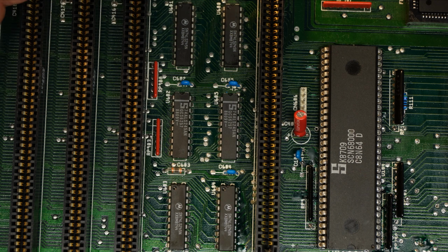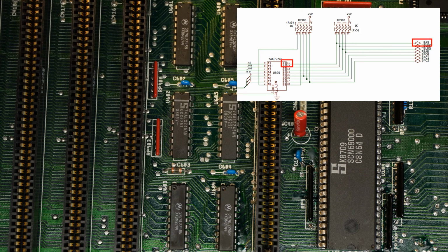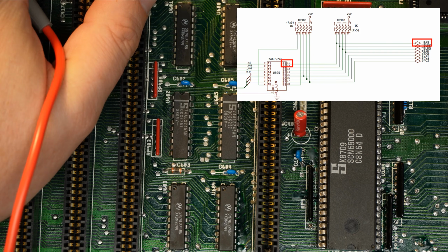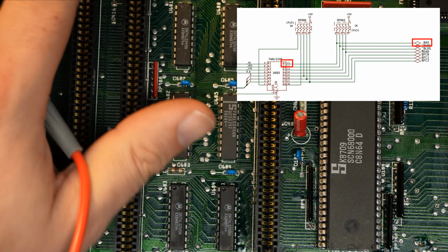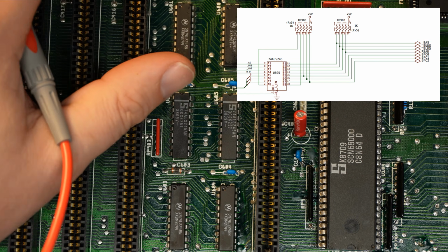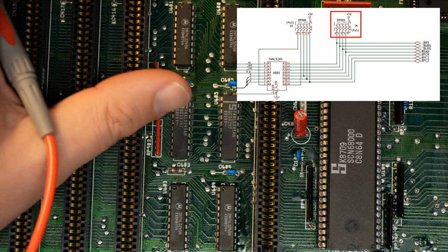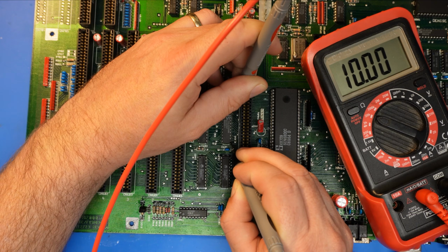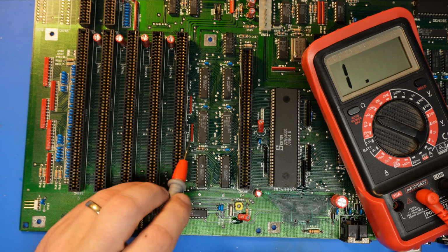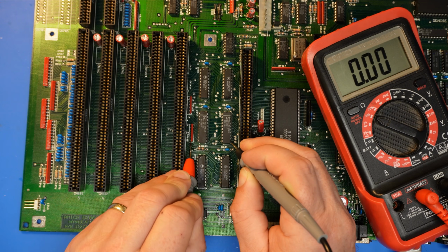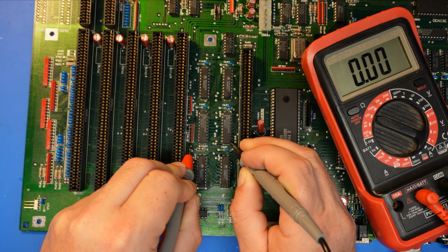And pin 11, if we look at the schematic, that is the BAS signal running to the Zorro side of things. Essentially, that's just the buffered address strobe line. BAS, I'm going to assume that's bus address strobe. Now, interestingly, the 6.2 schematics show a 1k pull-up on that. But if we measure that, well, you can see that's a 10k pull-up, and that's being pulled up by those two resistor packs there. It's probably this one, RP903, and yeah, that's a dead short there.